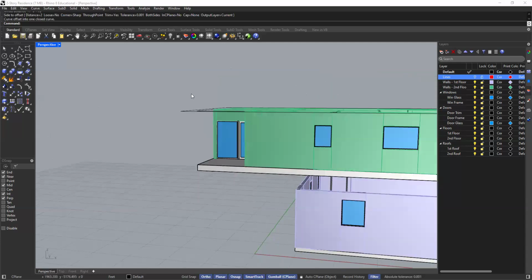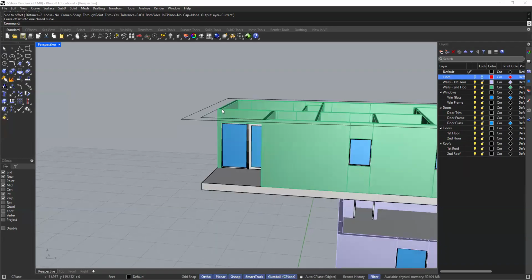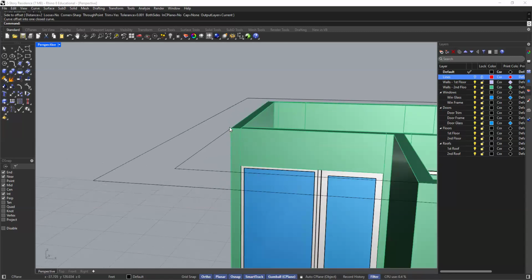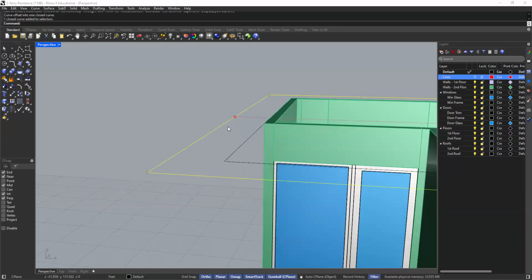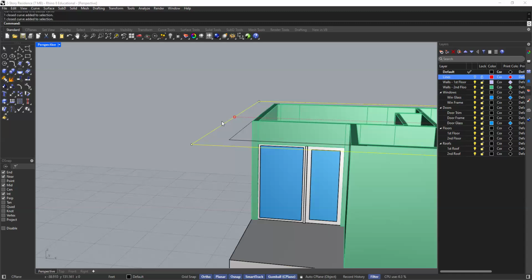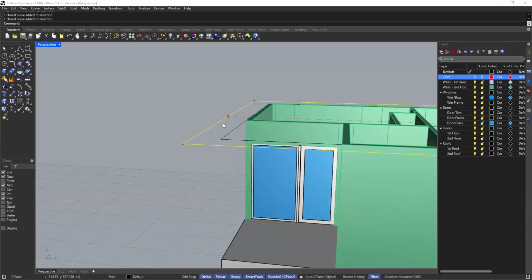Now I mentioned that we are using a 3/12 ratio for a hip roof. That means that the angle of my roof is going to go 3 inches up for every 12 inches out. So in other words, 3 inches up for every 1 foot. And so if we just did this overhang at 2 feet, that means that this overhang line is going to go down not 3 inches, but 6 inches because it's 2 feet.